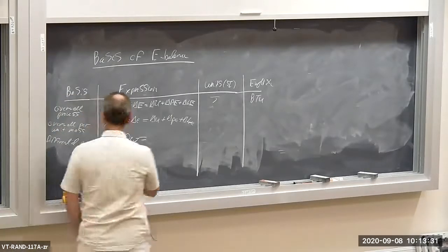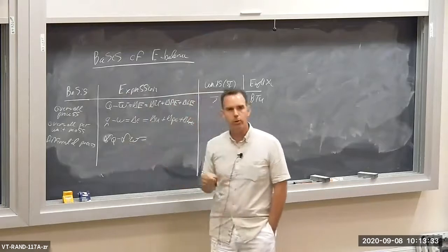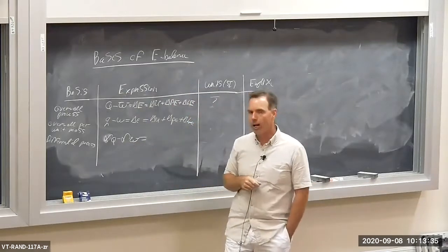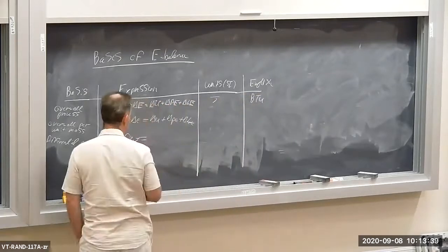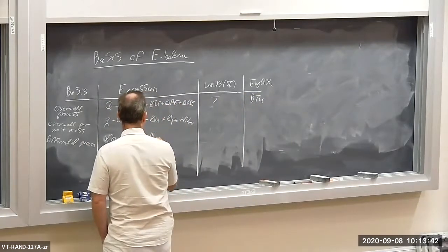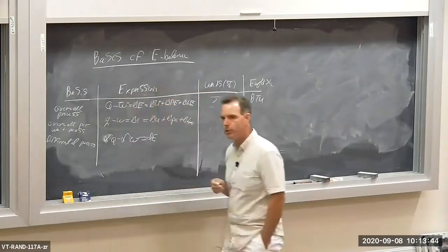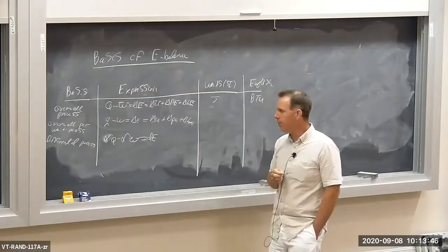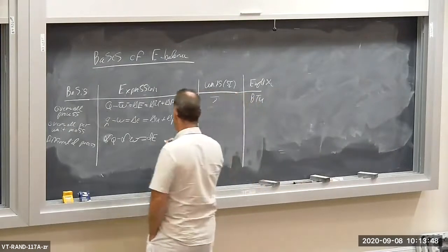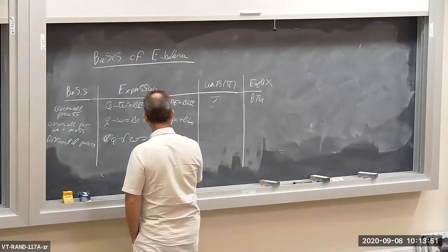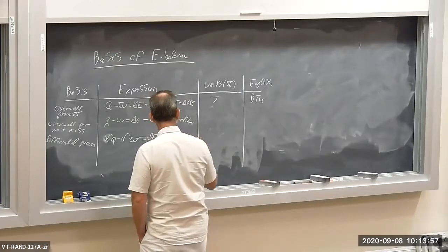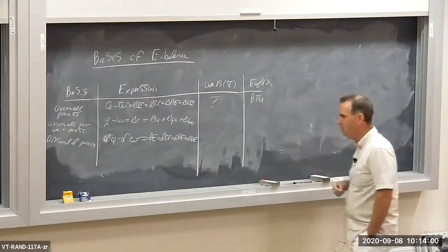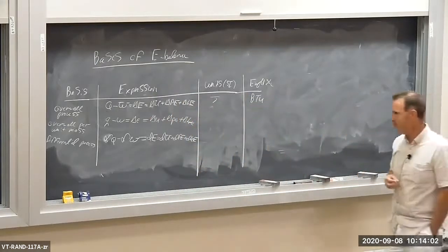So you don't write dQ and dW here, you write del or delta Q, delta W. And then I have dE. Energy is a point function, so it's dE, not delta E. dE, which is equal to du plus dPE plus dKE. Okay, that's the differential or infinitesimal process.